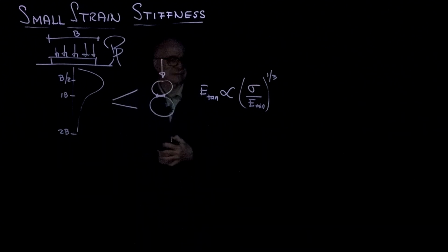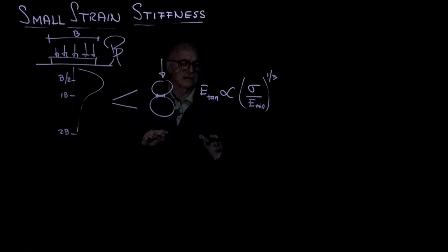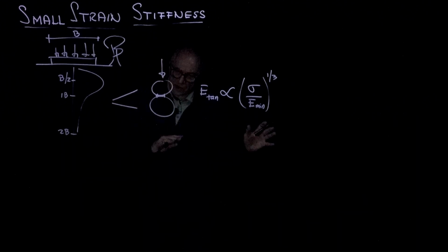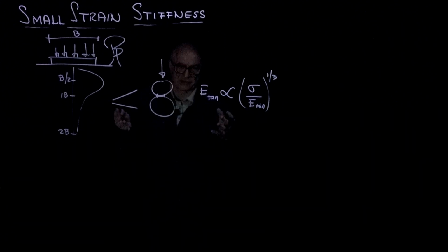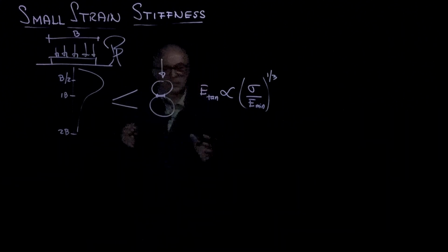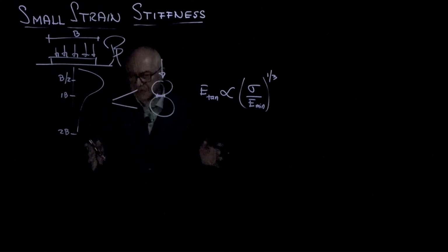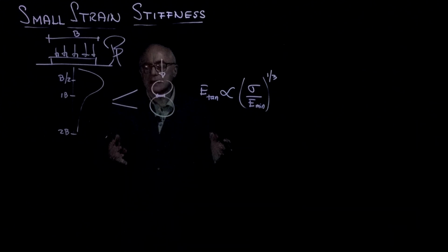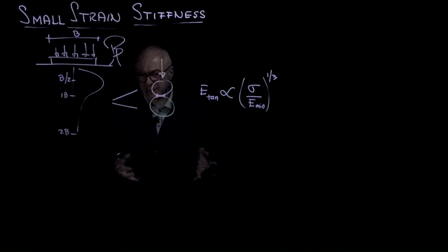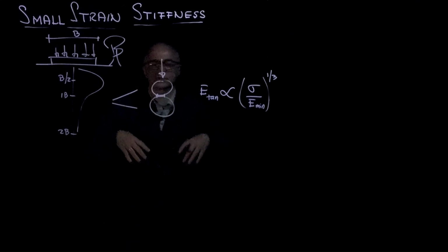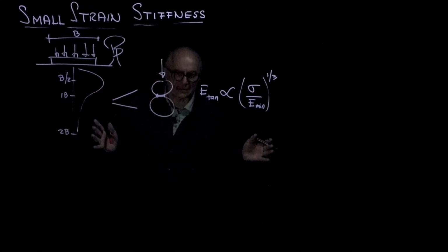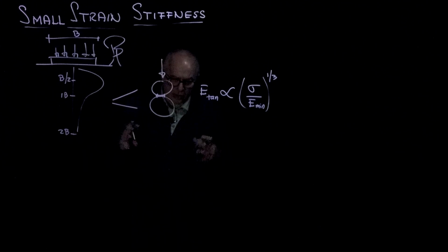The other element that is important to recognize is that when we do wave propagation, including in earthquakes far away from the source, and if there is no site amplification, that propagation is taking place at relatively small strains. And all our laboratory studies are based on wave propagation at small strains, probably in the order of 10 to the minus 7, 10 to the minus 10. Therefore, wave propagation preserves the fabric, does not alter the fabric.